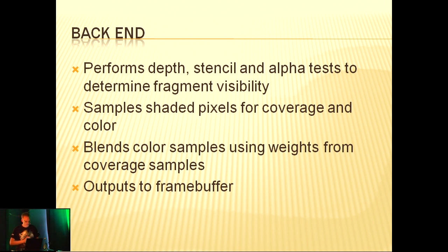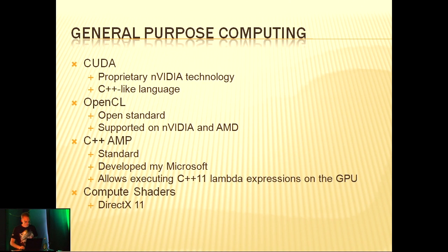And as a side note, the backend actually uses, or the CU has these export registers that are used for writing into the frame buffer. They're used for communicating between the compute units, the SIMDs, and the fixed function pipelines, and are also used for outputting the vertex colors, pixel colors, and stuff like that to the frame buffer.